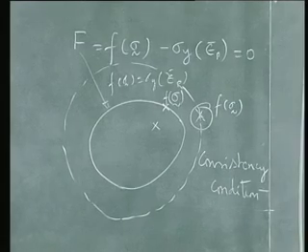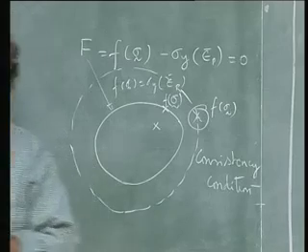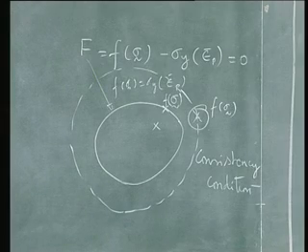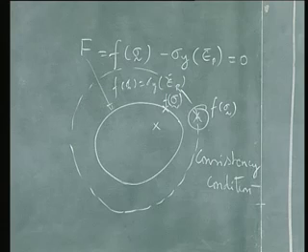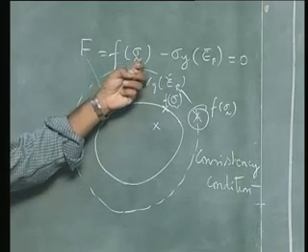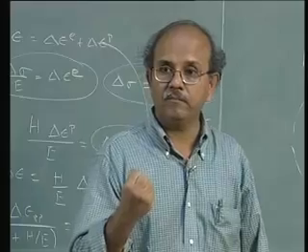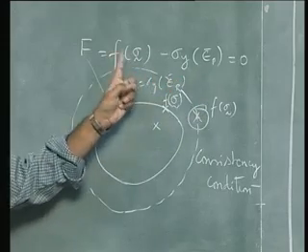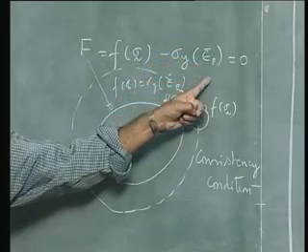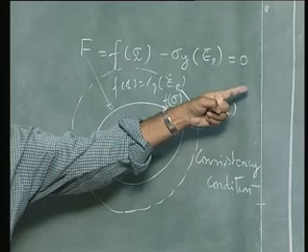Yes. If there is an outside, can a point lie outside the yield surface? The point cannot lie outside the yield surface at all, because what we are talking about is what is called rate independent plasticity, which means that when I increase the loading, okay, that means that I increase or change the first part of the equation, the material will respond with me, okay, and that results in a corresponding increase here, so that any increase here is compensated by an increase in the second part, so that the sum of it will always be equal to 0, right.